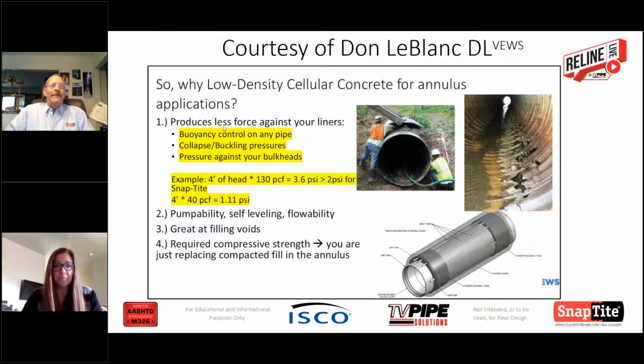Sure, it's all a matter of physics. Most of this boils down to a lot of engineering work, and you've got to have enough pressure, whether that's through pumping or through elevation and head pressure, to get that fluid to reach an equal level to get up into those voids. When we've done the dig ups, we found that a lot of those voids are truly filled, but there is a hydrostatic level there. If your void's much higher than your grout elevations, then that can be an issue.